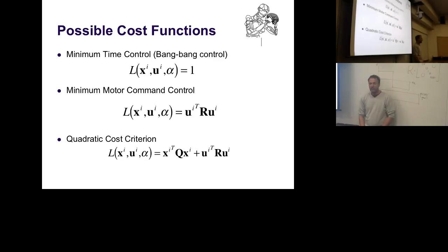But you also notice it's an arbitrary way of weighting things. Someone has to come up with weights. And you will see when you play with optimal control problems, these weights make a big difference in how things come out. And that gets us into this trouble in general with optimal control. We express our objective in some very strange parameter space. So here this matrix R, for instance. And you will see in a moment we put some state cost in there, and we get another matrix, which is the matrix Q, which says how much I should be penalized for being in a particular state. These parameters are not easy to set. It's nice if you can use the identity matrix or some simple rules. Often people basically tweak them so they get the behavior they want.